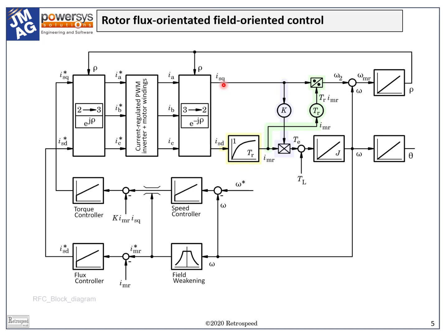Now, whereas the circuit diagrams in the previous two slides represent currents and voltages within the actual circuits, this diagram defines the relationships between signals representing the values mainly of currents but also of speed and torque. It is this type of signal diagram that is used to define the architecture of the microelectronic controller, and in some sense it captures the entire performance of the complete system.